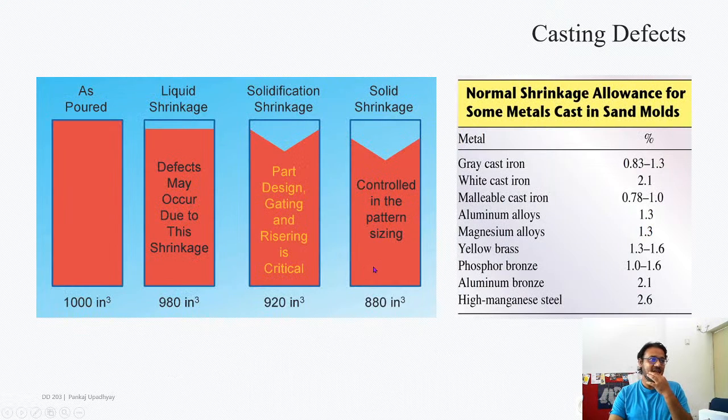Okay, the other thing that you have to understand is that the shrinkage is not uniform. It's not like a scale operation in a software. Rather, the shrinkage happens non-uniformly based on the thermal mass that is there. So this is a small diagrammatic representation of what exactly happens. Let's say it's a cylinder, and we've poured in the molten material in this way.